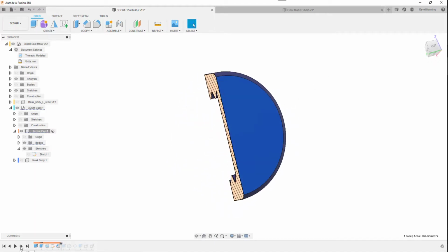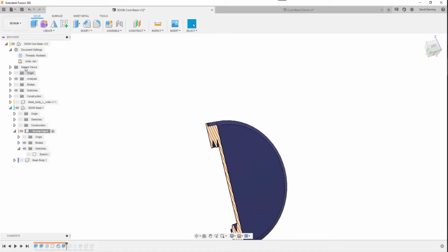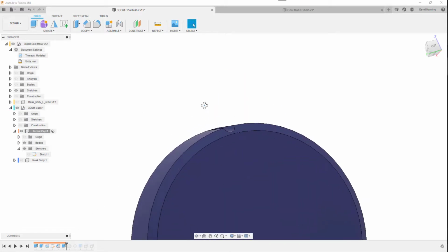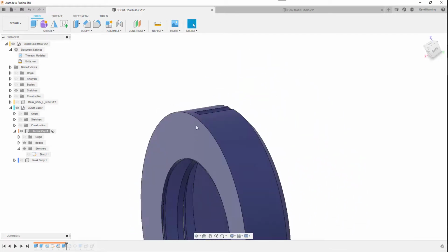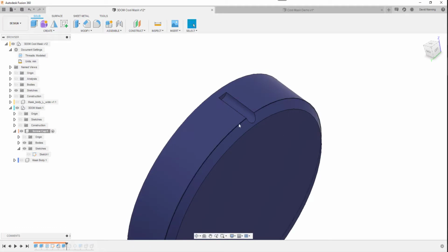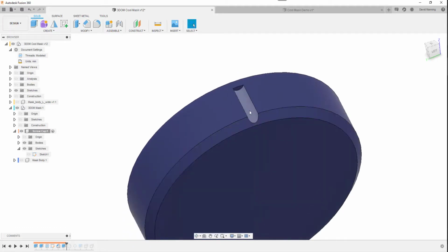So what we do is you get that sketch, and what I've extruded, let's get rid of analysis, one of those circles down a certain distance. Now I've left a deliberate space there because I think that looks better, and it helps a bit of structural integrity and gives us a low surface here. You can run that right through, does not matter. So once you've got that one, the next thing I do is I fillet these edges, which gives me a nice curve and a nice soft feel without being sharp, and then I pattern that around.